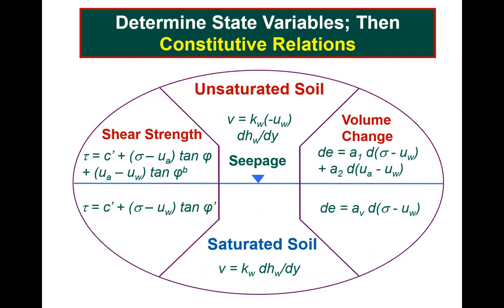So where do we start to develop a science based on the state variables that have been mentioned? Once appropriate state variables are defined, we can proceed to the determination of suitable constitutive relationships. The term constitutive relationships is used for any equation that is written to link state variables through the incorporation of an appropriate soil property and/or appropriate soil property functions.